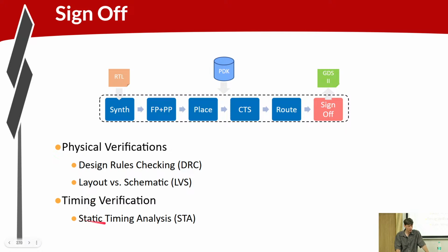Timing verification is the process of analyzing the timing statically. So you're analyzing the delay on all the routes. As I said, the upper level routes have less delay than the lower ones for the same distance. You're analyzing the delay through the cells. All of these things are characterized with a static number that represents the worst case delay, and you're essentially just adding up all of these delays to make sure that every path in your model meets the required timing.